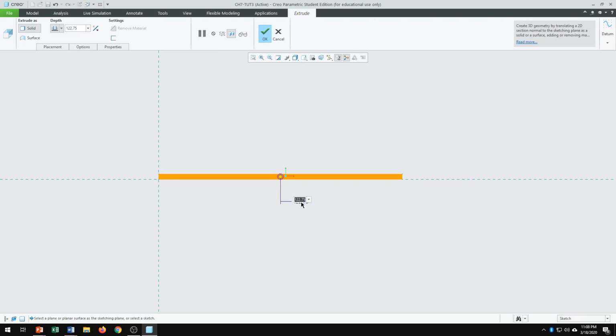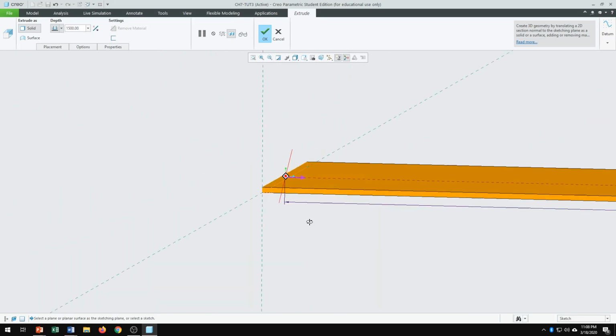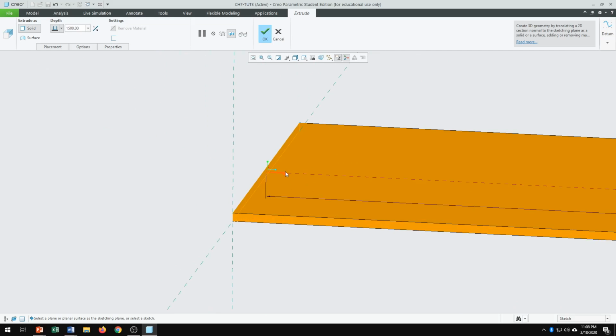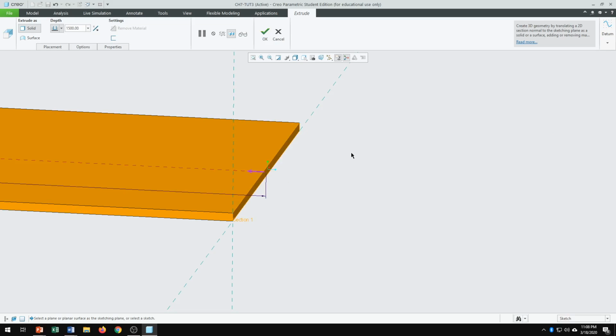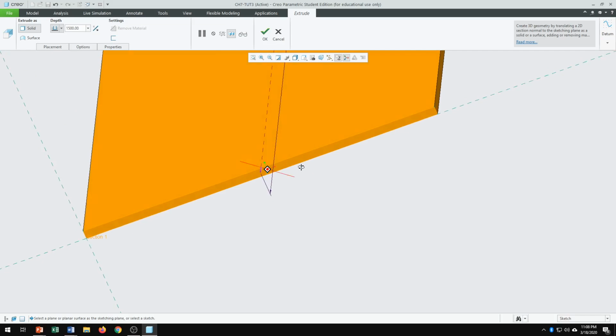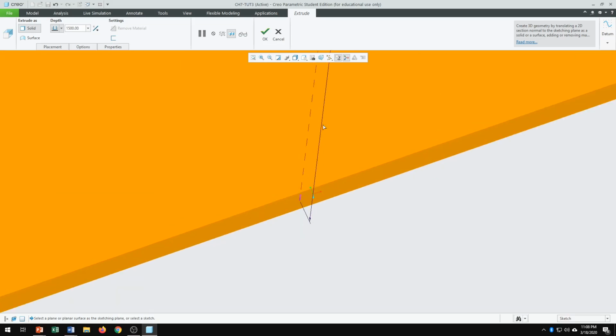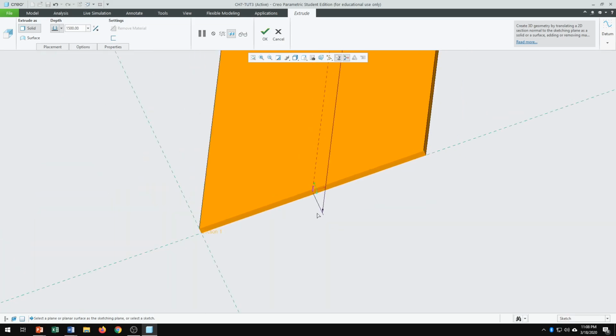And now we're going to give the thickness of 1500. Now this part, you got to pay attention to this part. All right, so I'm going to reverse. If you look, reverse this arrow, and then hold the middle click and rotate them, and try to observe this edge here. We have an x-axis and y-axis intersect with this left end, not the right end. So the arrow is in the direction that we're going to create the thread, for the tire.